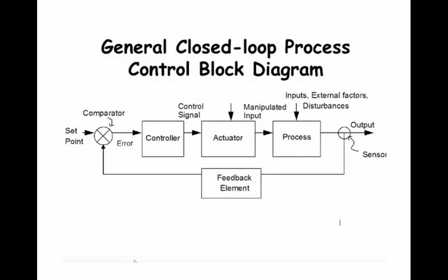Finally, we have the actuator. This is the element that converts the control signal into an action that manipulates the input. Example actuators include relays, solenoids, solenoid valves, and motors. So this simple block diagram with each of the main elements will be covered across the semester with problem solving for fluid heating, liquid level and flow, mixing tanks, bioreactors, etc.